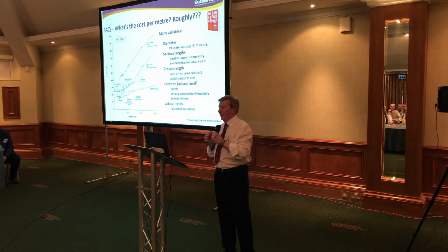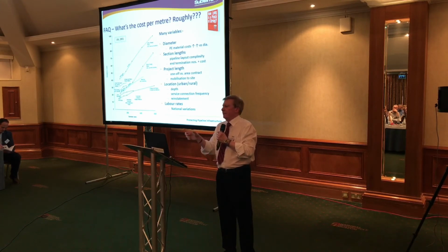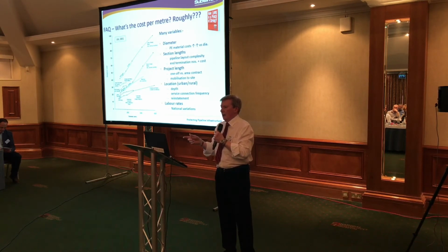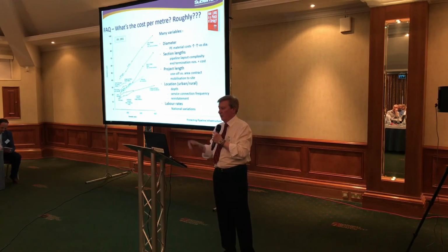That works better where you have long lengths. The project length itself can be important. Whether you have a one-off short project of 50 metres or a big project of 5 kilometres, because of the influence of mobilisation to site. I once did an exercise like this for one of my clients, where I looked at the costs of doing 100 metres compared with 1,000 metres. I think it was a DN 500. The cost for the 100 metres per metre was 3 times that of the 1,000 metres, and that just illustrates the point. The location is important.